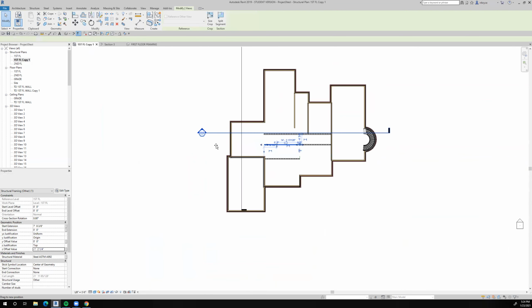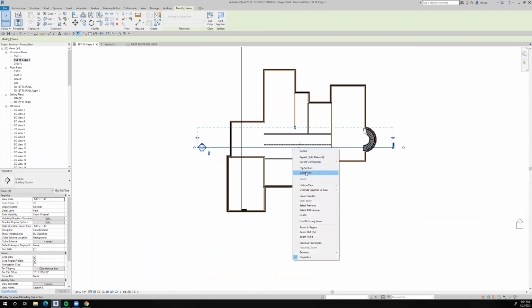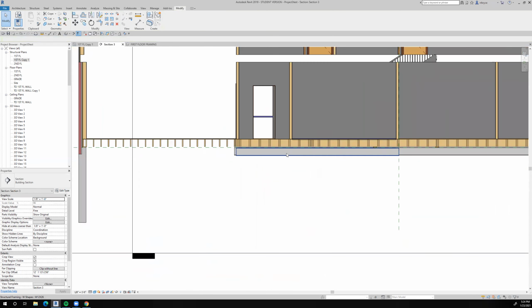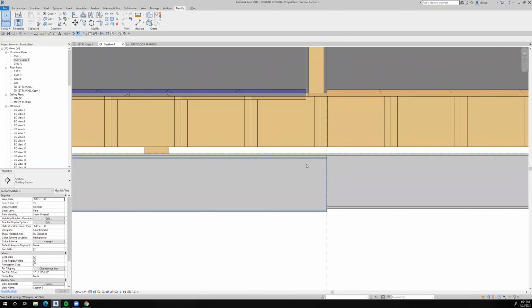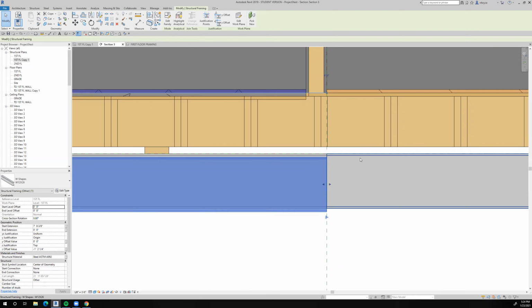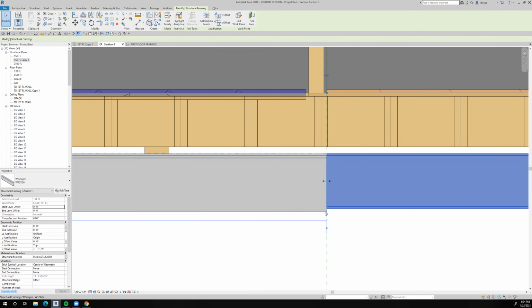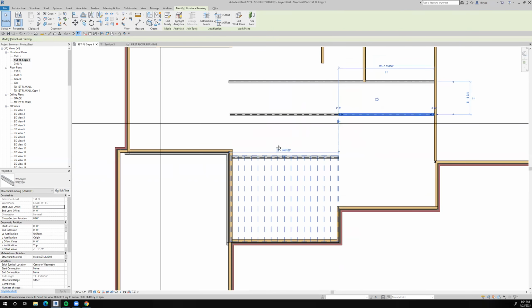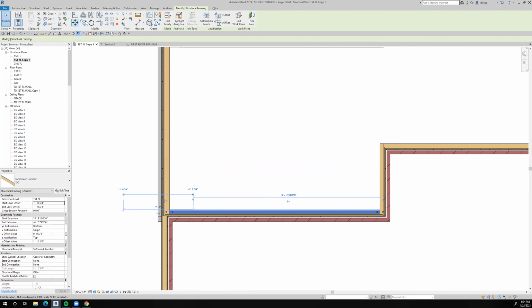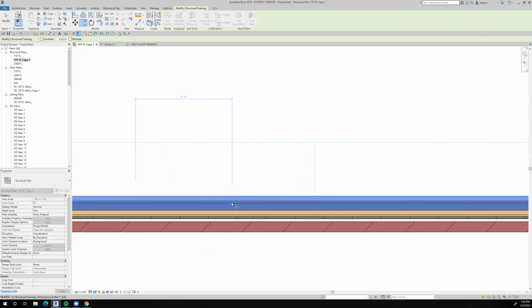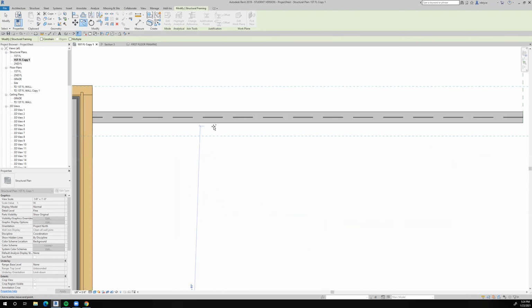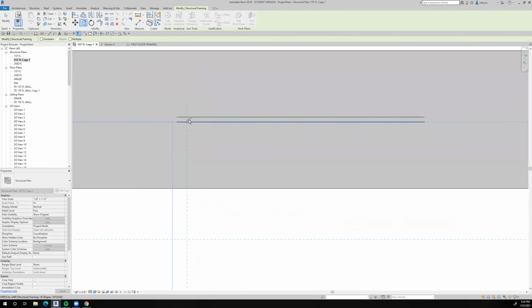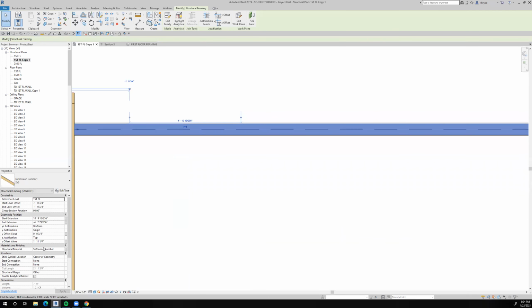But just to be sure, let's go take a look and see if what I wanted to happen actually did in fact happen there. And yep, see, here's that beam that I just dropped down, and here's the beam right next to it. We split that beam right here. So it's dropped down 3/4 of an inch because the floor is dropped down 3/4 of an inch. So I'll go back here to the first floor. And now I can copy this guy, copy him from the center of that 2x6 to the center of here, but it needs to go down that same amount.